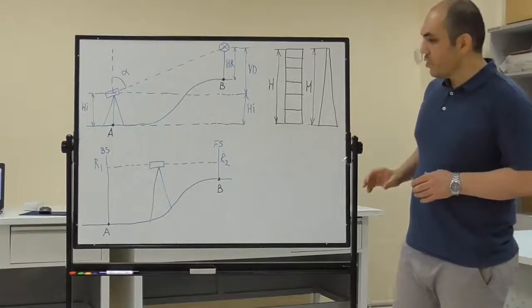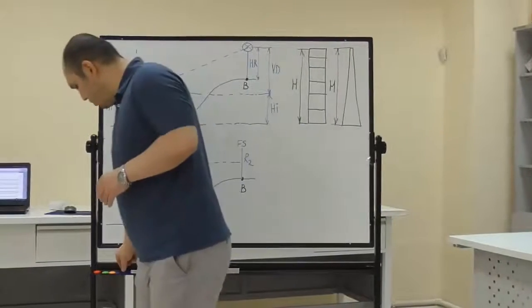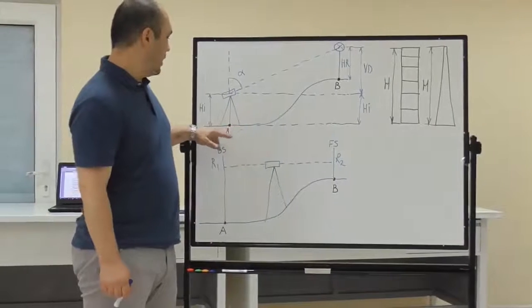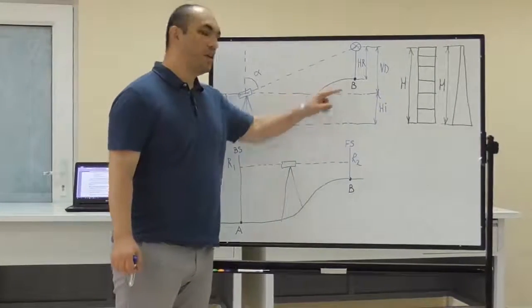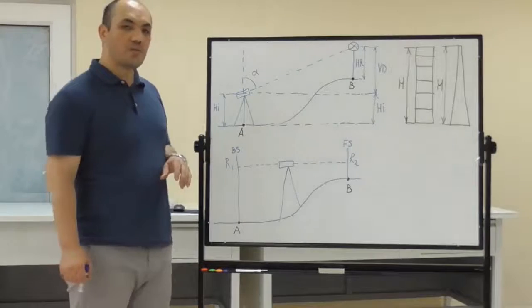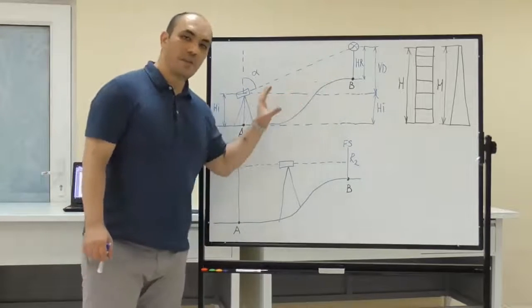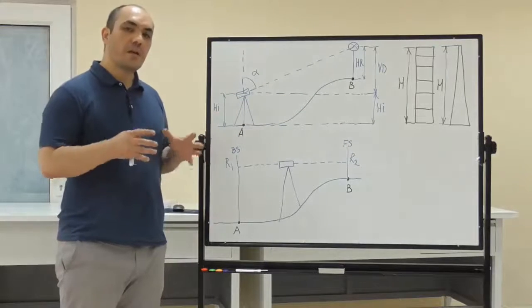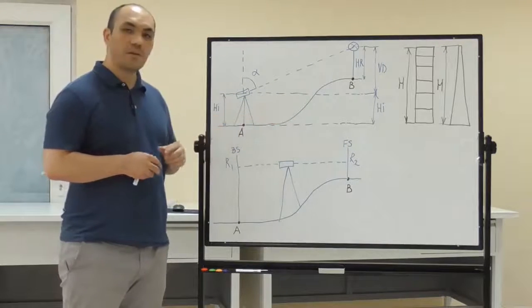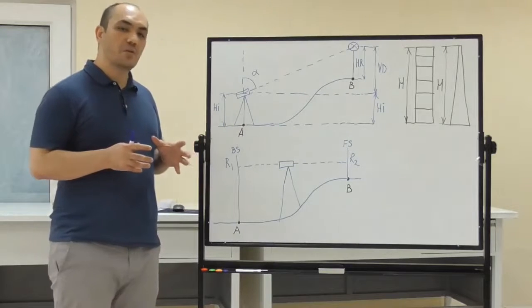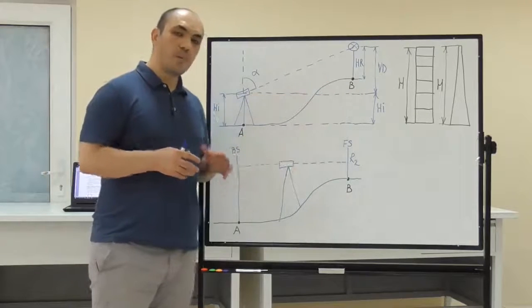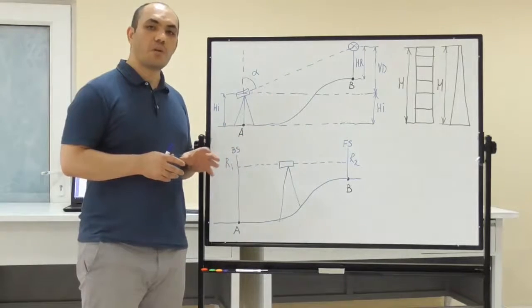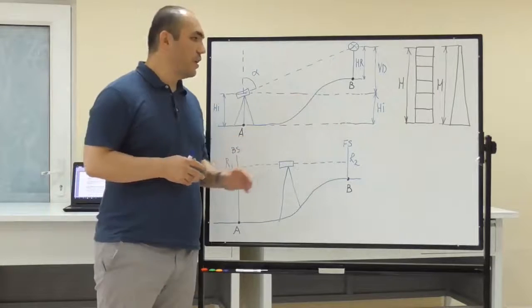Apart from this, trigonometric leveling is used to identify the relative height between point A and B in hilly grounds or hilly terrains. This relative height is necessary in hilly ground when we are planning new roads or when we're locating sewage pipes or water supply pipes.